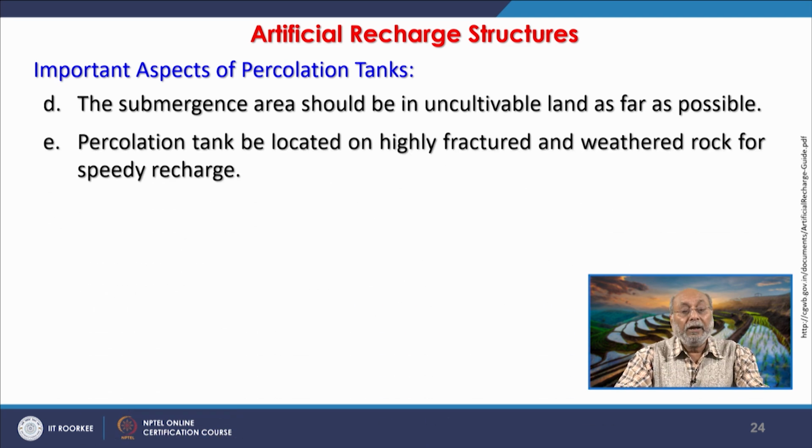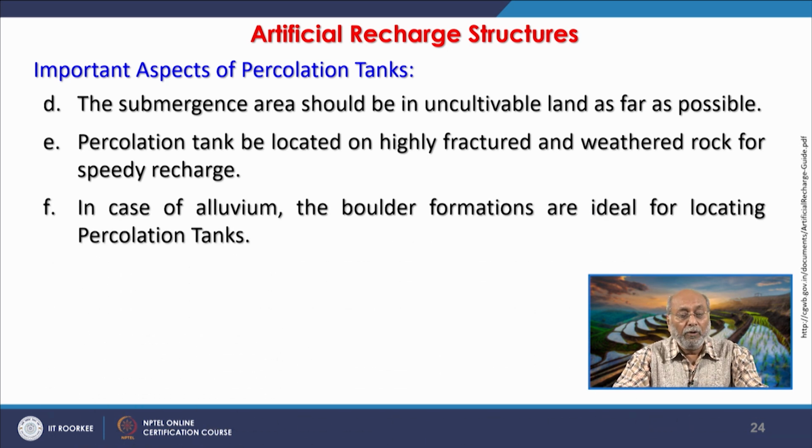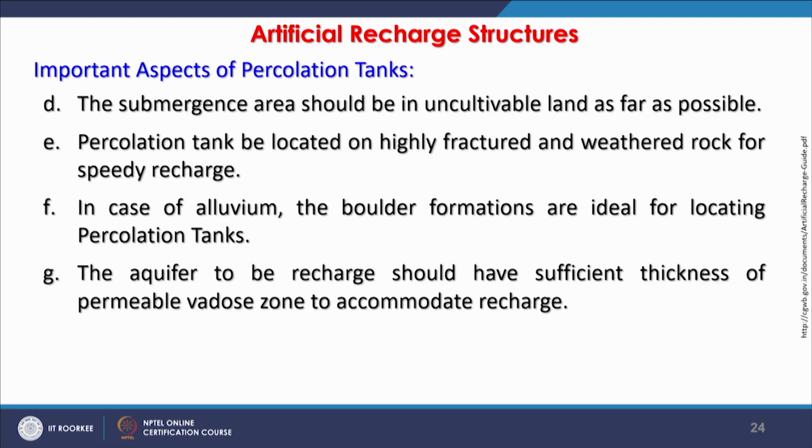And further, percolation tanks should be located on highly fractured weathered rocks for speedy recharge. If these percolation tanks are constructed in alluvium or where you have boulder formation, then such areas should be preferable if that choice is available. Alluvium, or alluvial fill valleys, you can find along the rivers, streams or rivulets. Those areas are quite good from a recharge point of view.